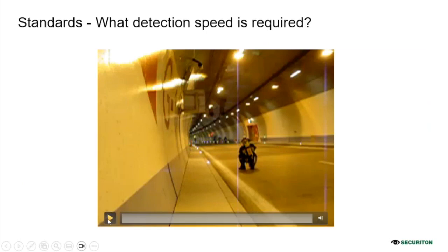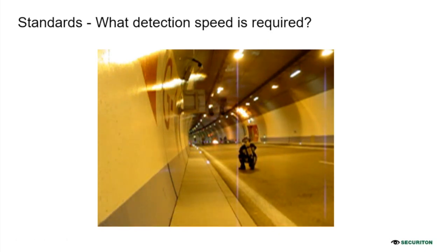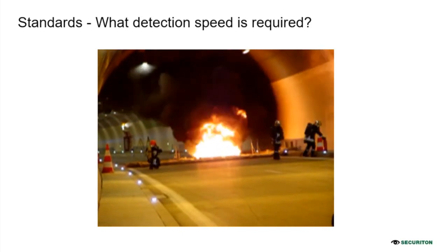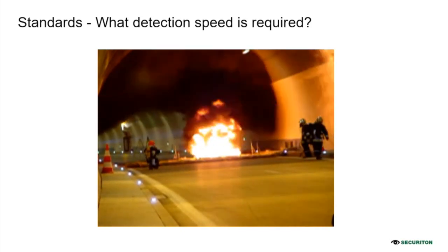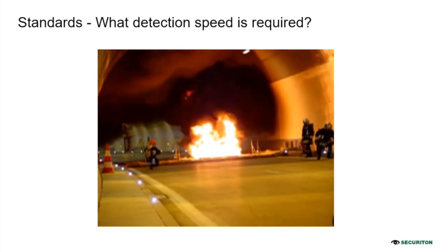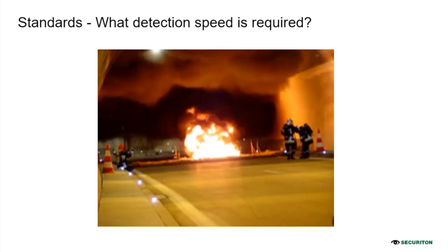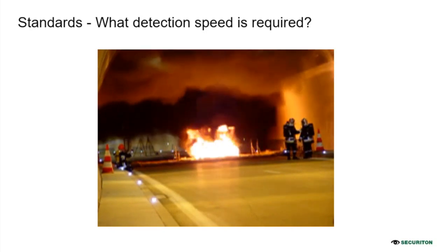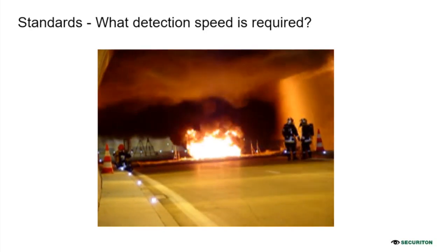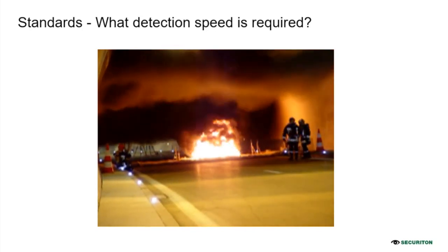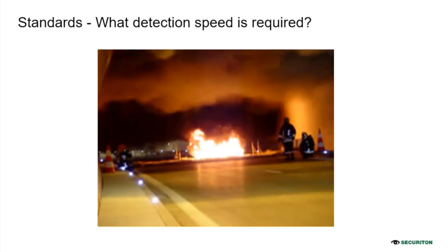This is a normal typical fire test, which is done inside a tunnel by the fire brigade. In this case, the fire detection system was switched off just to see how it works when we are not triggering the ventilation system. So you can see after 10-15 seconds, a lot of smoke is going up. The ventilation system is not triggered, so therefore the smoke is expanding very rapidly. And we see even the cameraman will be surprised.